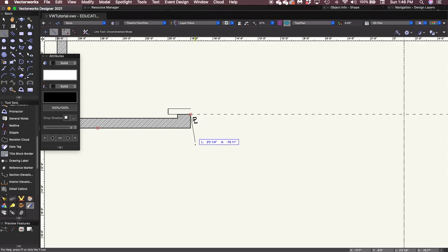I'm going to click once and drag it straight down to start my line. I'm going to tab into the floating display bar, and I'm going to make this length 4 feet. Great, there's my circle. I'll hit Shift and click here to set that point.